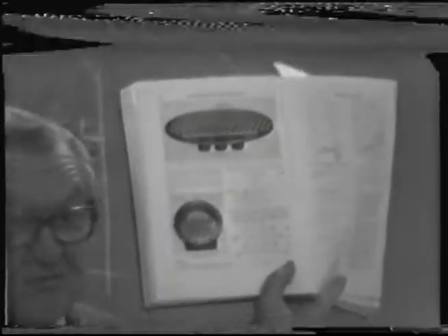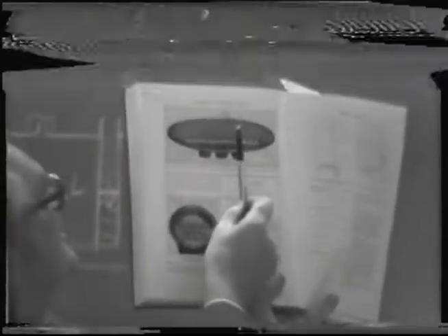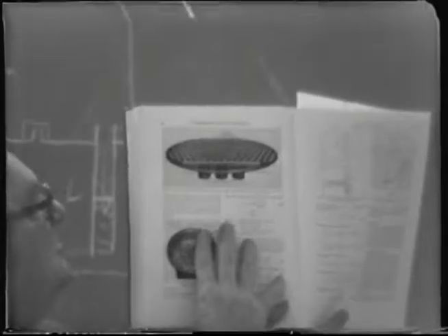Instead of having the downcomers project upward to form the overflow weir, they are simply formed by this chord weir, as it's called. You can see the backside of the plate here, or possibly you can see where the flow comes down, descends on a blank part of the plate from the tray above. So it flows across these bubble caps and on down. And so here we have 3 downcomers on each tray in that particular design.